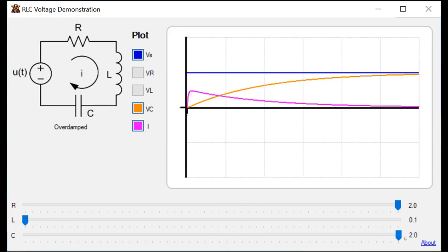Now there's 2 different time constants, one controlled by the inductor, which is small, one controlled by the capacitor, which is large. And this is called an overdamped response, where you've got 1 exponential plus another exponential. So that's the intuition, very roughly, about what's going on with the second order circuit, is that it can have three different approaches. It can look like a sinusoidal thing that's oscillating, decaying away. In the critical region, it can be approaching its final value as rapidly as possible without oscillating. And then in its overdamped region shown here, it can be approaching its final value, but not rapidly and not oscillating.